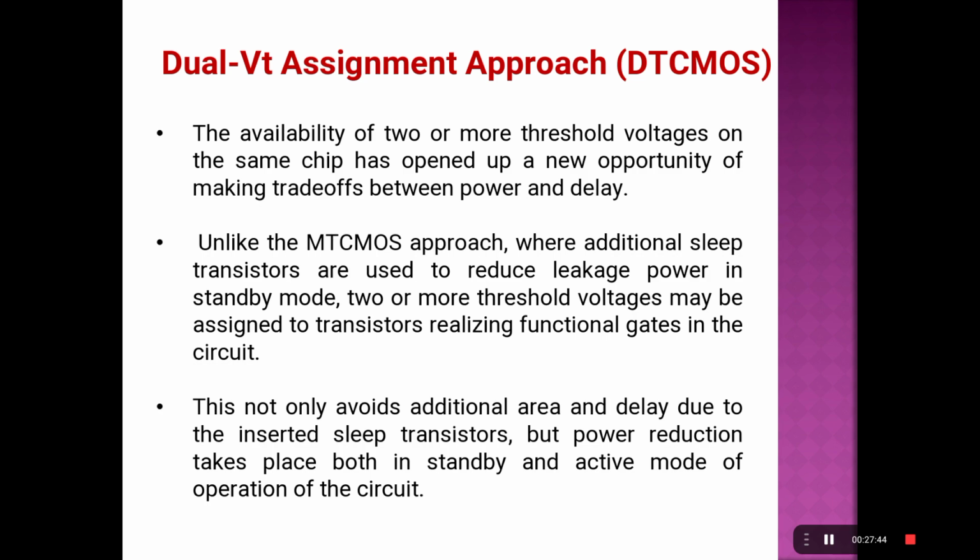The availability of two or more threshold voltages on the same chip has opened up a new opportunity of making a trade-off between power and delay. So that is very important. Unlike the MTCMOS approach, where additional sleep transistors are used to reduce the leakage power in the standby mode, two or more threshold voltages may be assigned to the transistors realizing the functional gates in the circuit.